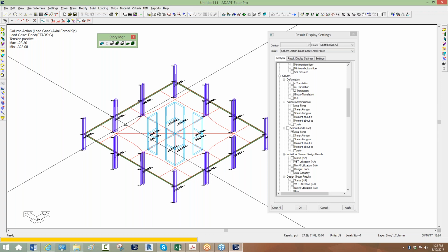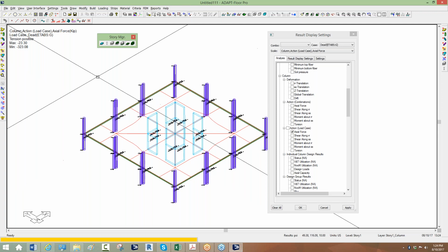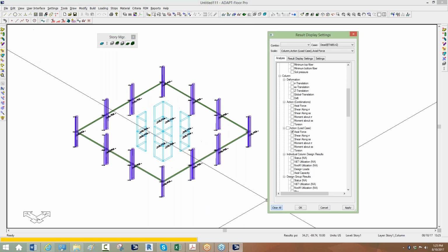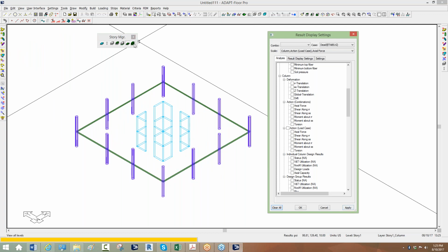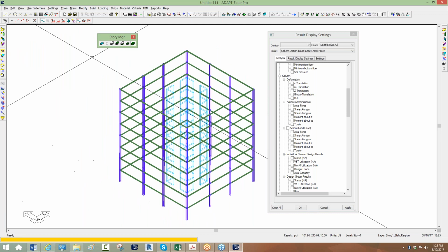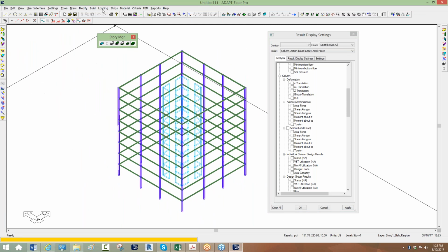So one of the ways you can use the data that's imported from Etabs into Builder is being able to reanalyze the frame inside of Builder using the applied loads coming from Etabs. There may be reason to do that. Maybe you want to compare frame results between both programs, so using the same level of loading. So to do that, what we need to do is go back to our multi-structure mode. Remember, building loads are only solved for when we're in building mode or full structure mode.